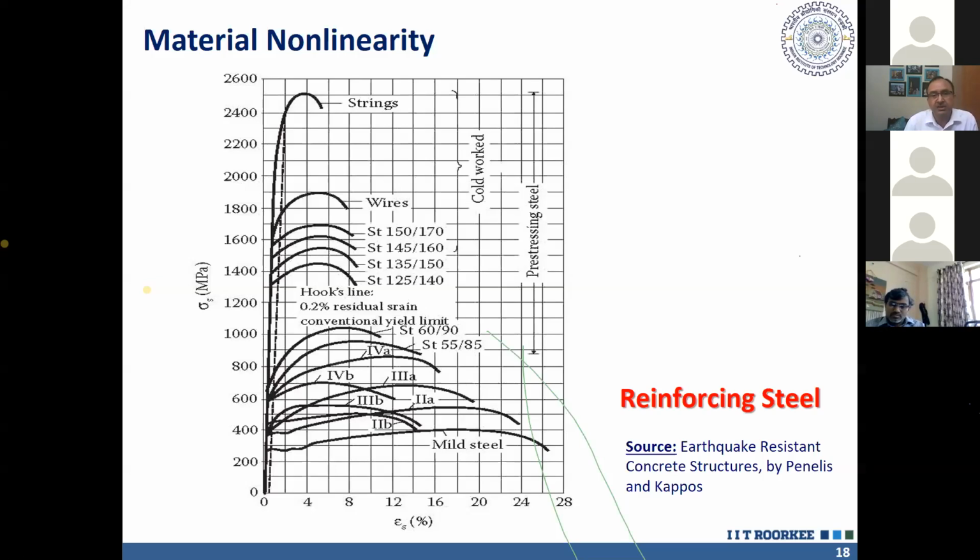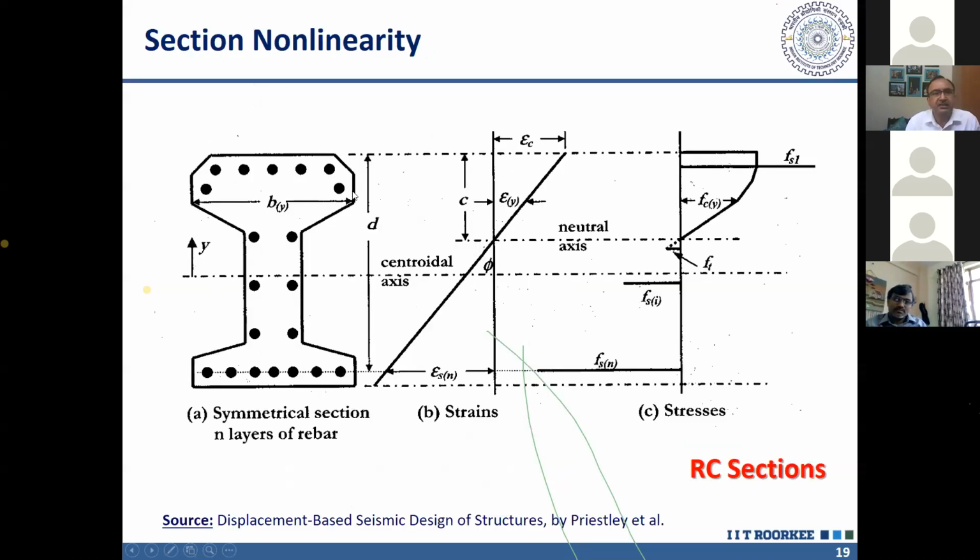As I said, we are designing only for 20% of the forces. So 20% we depend on strength and 80% we depend on ductility. So ductility is even more important, and we will not like to compromise on ductility. It's very important that whatever steel you are using, either in conventional design or performance-based design, that steel should have a satisfactory level of ductility. And that is specified in the code, that it should have at least 14.5% elongation.